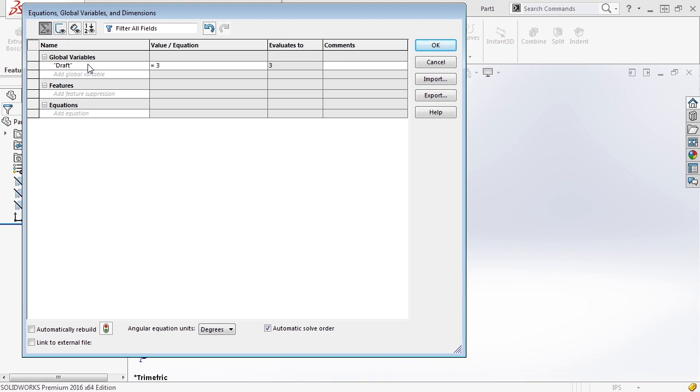Now, if you have a very big part, something that's considered a deep draw into a mold, you're going to have ample draft to associate with that. If you have a very thin, very small part, you can get down to 0.5 degrees, 1 degree draft and be okay. Sometimes you can even get away with no draft if you understand that you're going to have tool drag marks on the outside of your part. There are also things to consider like texture. If you're going to have a heavy texture on the outside of your part or the A side, you're going to have 3 to 5 degrees draft minimum.